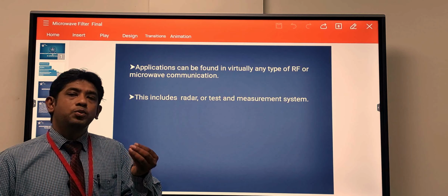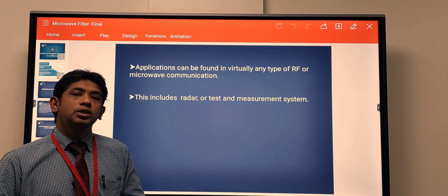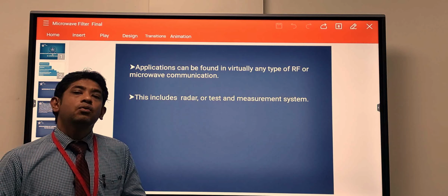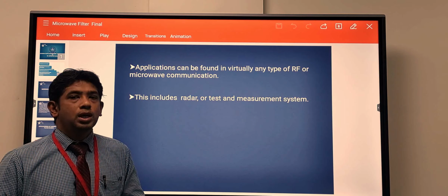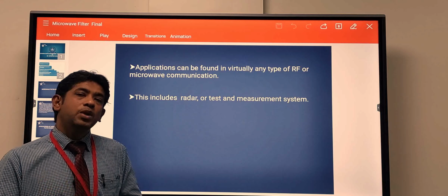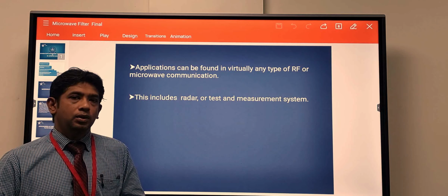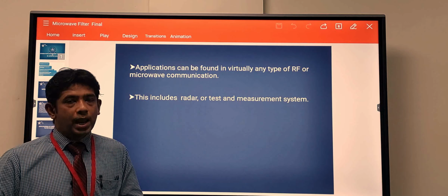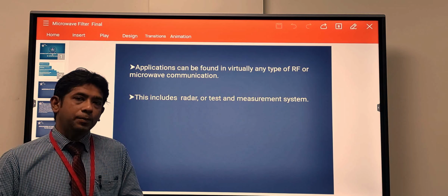A more modern procedure called the insertion loss method uses network synthesis techniques to design filters with a completely specified frequency response. The design is simplified by beginning with a low pass filter prototype that is normalized in terms of impedance and frequency.